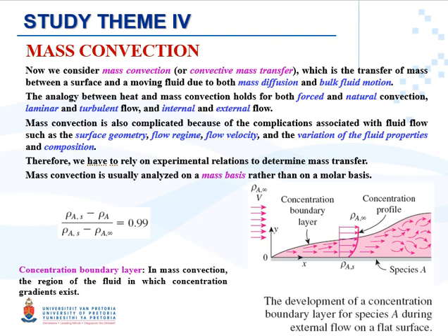But do you remember how, in convection heat transfer, the fluid motion would play a critical role? Fluid motion increases heat transfer significantly. How? By removing the heated fluid near the surface and replacing it by the cooler fluid further away.